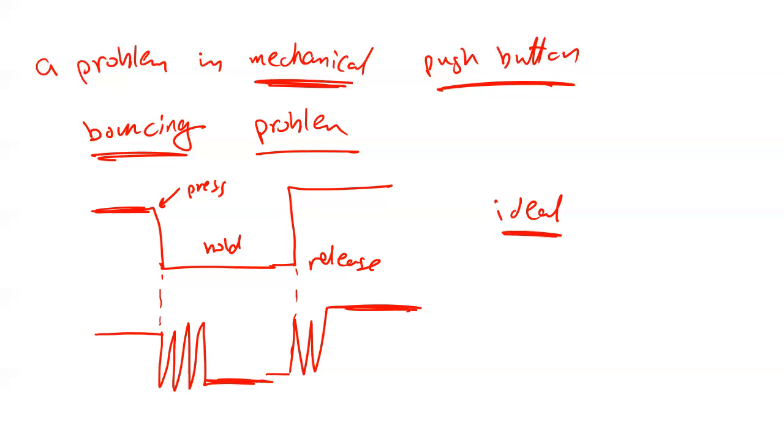I didn't explain yet how you can solve it, I'm just making a definition. So the way I told you, when you press a button, it's going to be something like that. In reality, no. It has some mechanical parts, so the switch is not going to move right away. There is going to be some bouncing before it opens, because of the spring, the mechanical part. Okay?